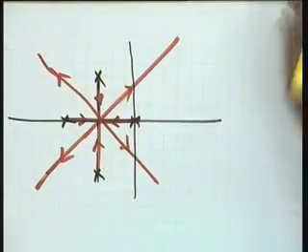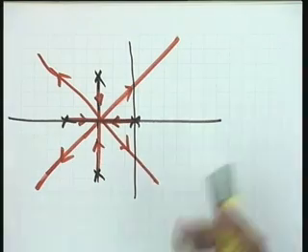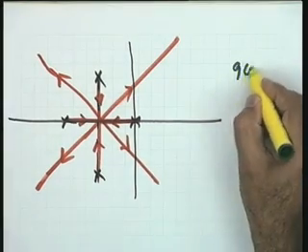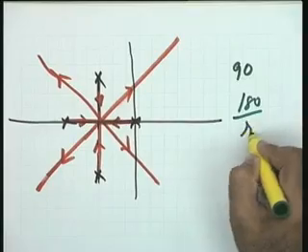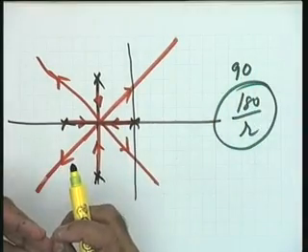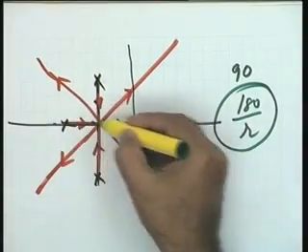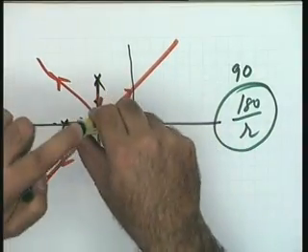If the 4 are symmetrical, you are getting this root locus plot. So in this particular case, his question was whether the roots always break away at 90 degrees. I say that the roots break away at an angle of 180 divided by r, where r is the number of branches which are meeting. In this particular case, 1, 2, 3, 4. 4 branches are meeting at this particular point.